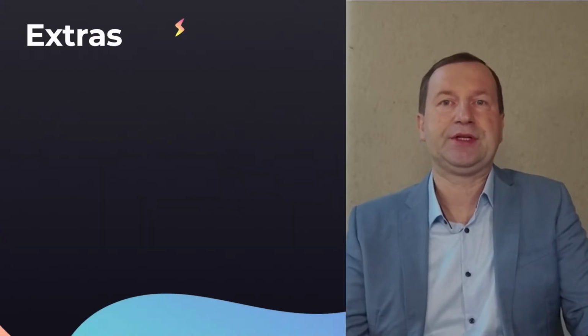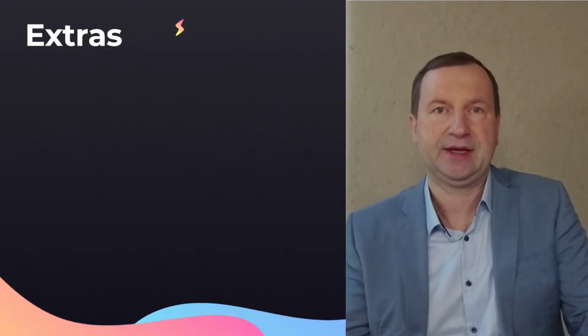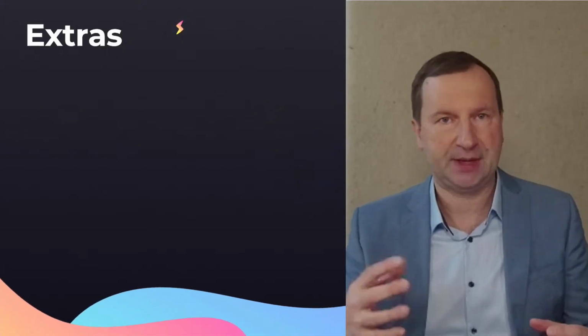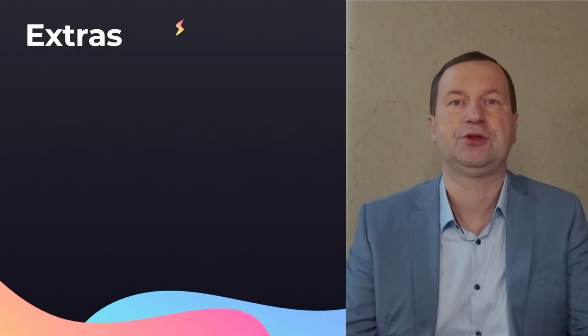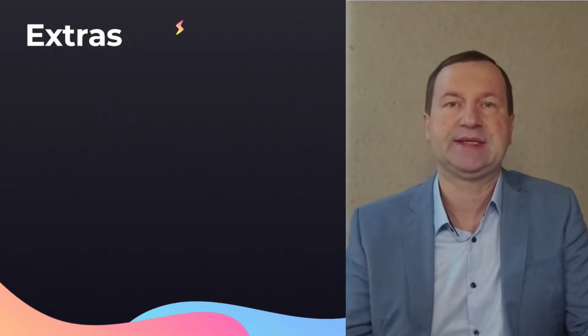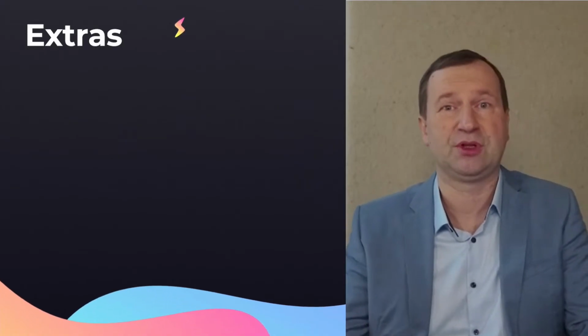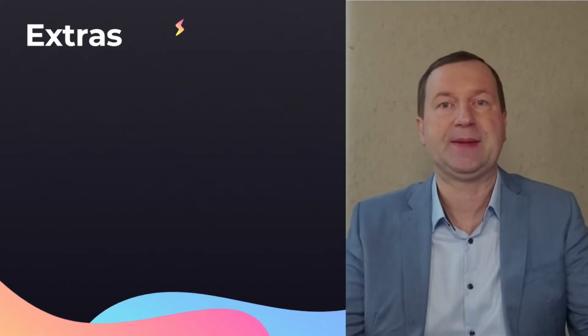Certainly, it's not the full list of features available in Visualize SDK. Our other features include fast transform, which allows real-time metrics application and real-time isolation or geometry pipeline. Sectioning is also worth mentioning. Visualize SDK provides GPU sectioning, which is very fast but offers only a visual result of the section, and CPU sectioning, which is slower but provides the section geometry as a plain shell or polyline.